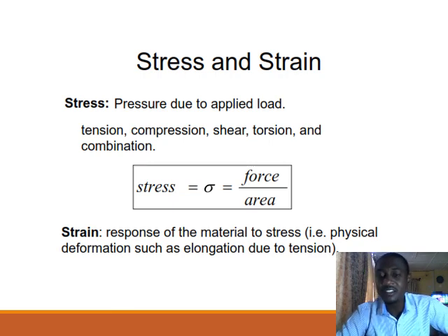In understanding the behavior of a material as it responds to a mechanical load, you have to start by understanding the relationship between the applied load and the deformation. The quantity that describes the effect of that applied load is stress, and the consequential deformation resulting from the applied load is strain. So these two are quantities that allow us to quantify the effect of the applied load, and the resulting deformation from the application of that load can also be quantified by understanding the strain.